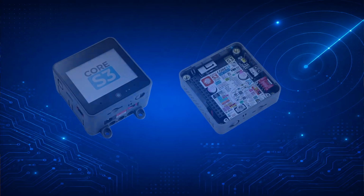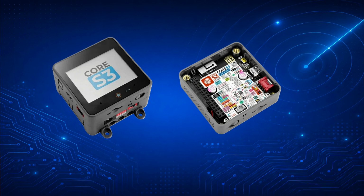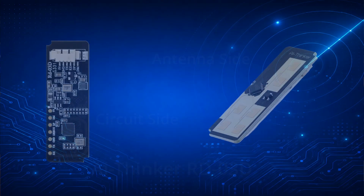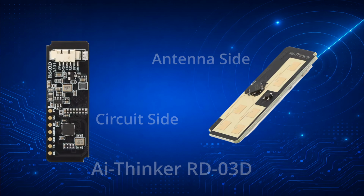The project is built around two main components. The first is the M5Stack CoreS3. It contains an ESP32S3 processor, a color touchscreen, Wi-Fi, storage, and the supporting hardware needed to operate as a compact standalone controller. The second component is the 24 GHz mmWave radar module. Unlike a basic motion detector, this sensor can provide position and movement information for detected targets.